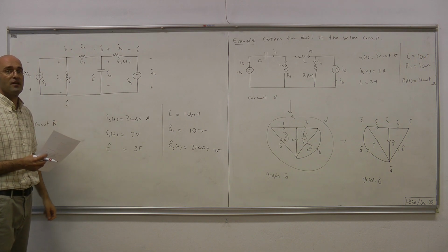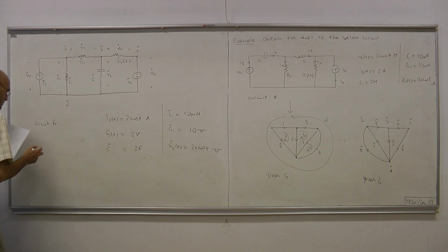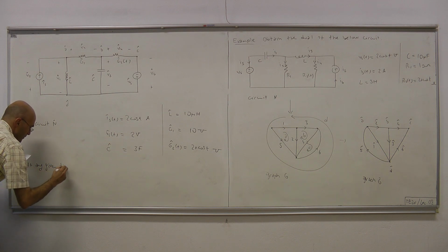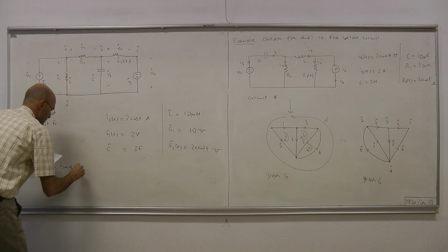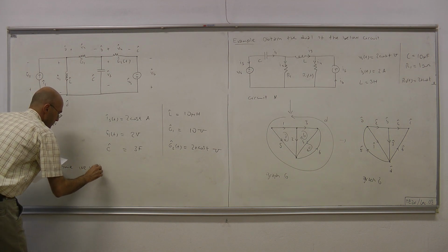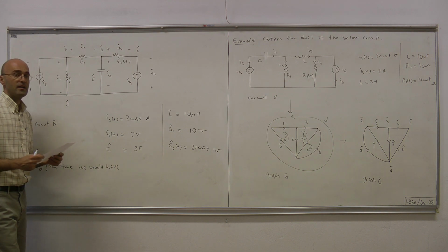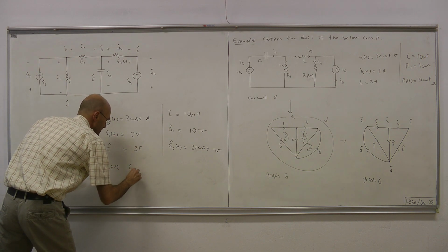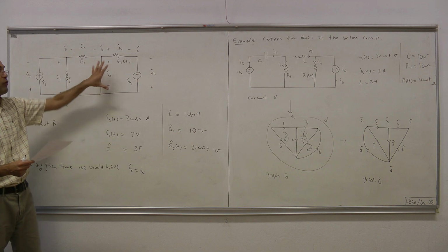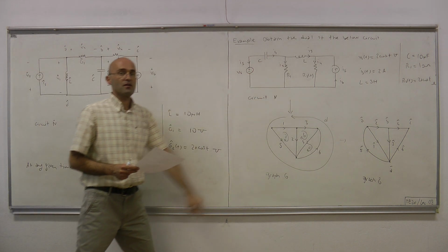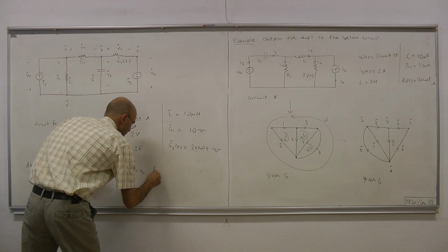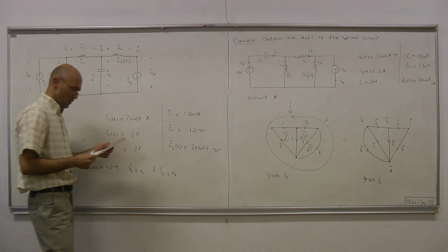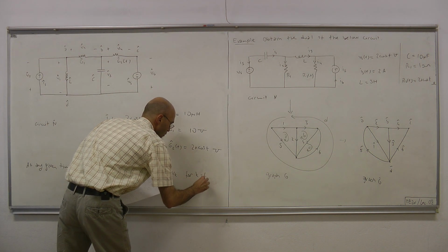And finally, what's the relation between this circuit and this quite different circuit? I'm talking about the physical relation. The physical relation is as follows. At any given time, now we're considering those 2 circuits simultaneously, you would have Vk hat equals Ik. Okay. Voltages here equal the currents there and vice versa. And Ik hat equals Vk for all 6 branches.